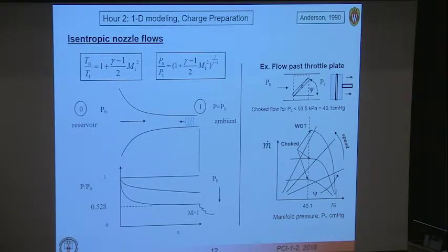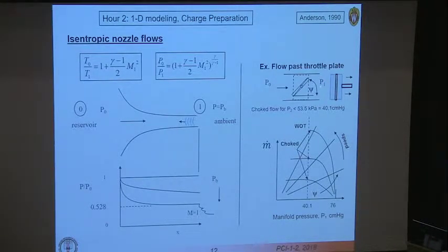So you can see an example of that in your intake system here. Here your piston moves down and creates a lower pressure region. That means you now want more flow to pass your throttle plate. If for some analysis you find that the pressure downstream of the throttle plate is less than 0.528 times the supply pressure, you'll have choking.